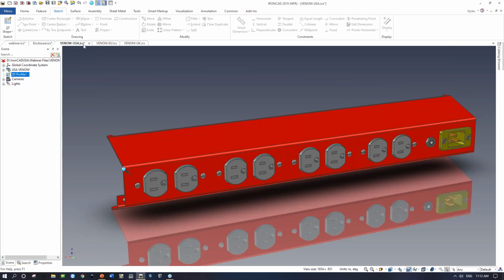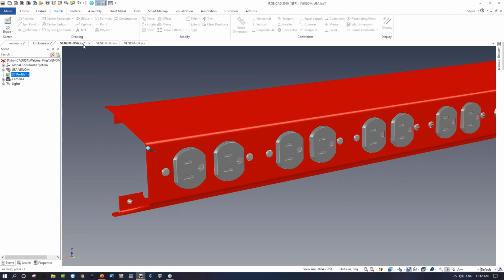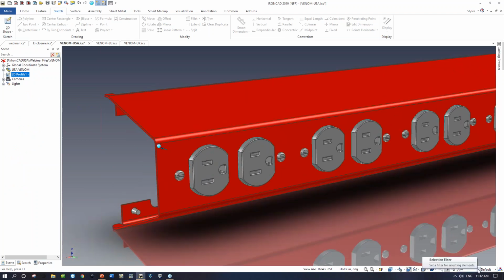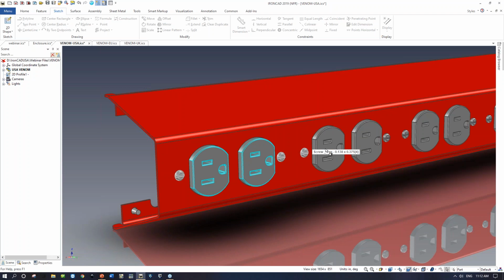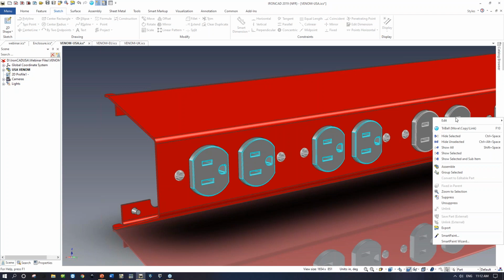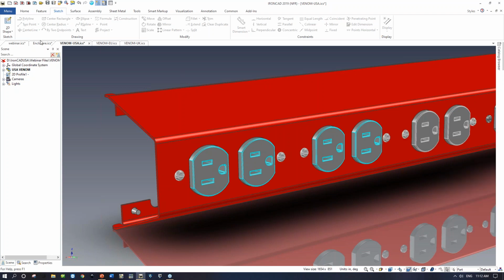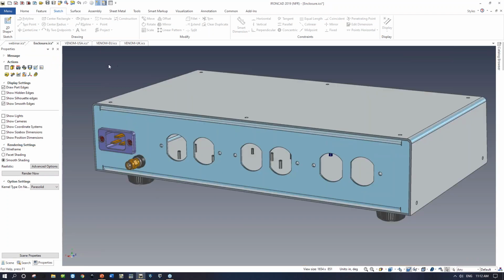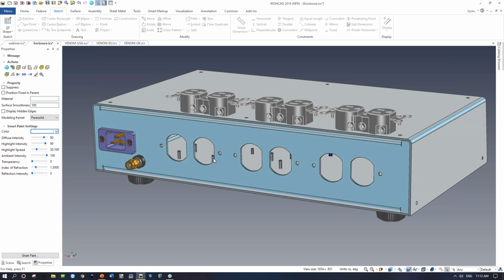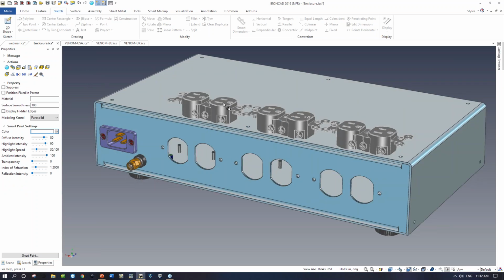I'm going to do the same thing again now, and instead of the sketch geometry, I'm going to be even smarter. I'm going to come in here and say, you know what, I really only want to take a part, and I'm going to take this screw right here. Shift select. I want all of this, and I'm just grabbing this geometry in the same way that I would use Microsoft Word or anything like that, saying, okay, take this, and I need you to copy this geometry from this file, and I want to take it back to this file. Control V, paste it in, and look what's happened. Now I've got the geometry from one file directly copied into this one.